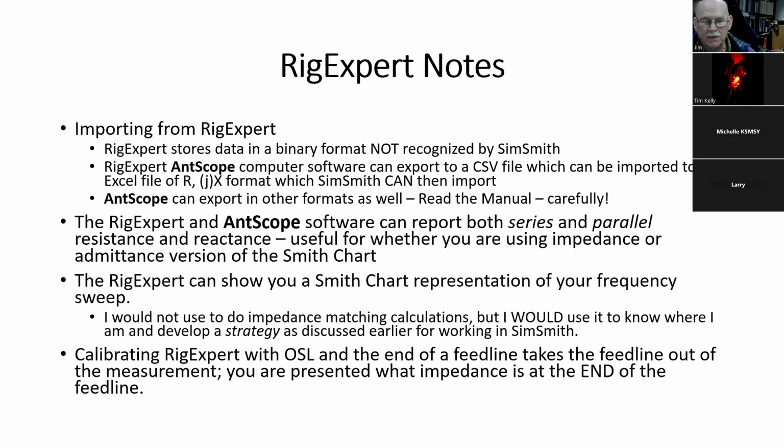But with Rig Expert, you get a computer program, which I have on my laptop and my desktop, called Antscope, that will read that data, will also let you drive the Rig Expert, and then you can export that data to a comma separated variable file, CSV file, or an Excel file, which SimSmith can import.